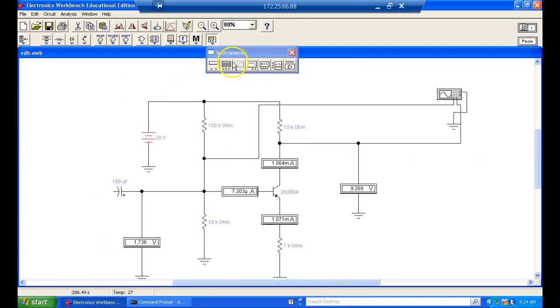So we'll come up here and bring in a function generator. Now normally to troubleshoot these things, audio is all over the place. So to troubleshoot these things, normally we bring in a known waveform. If I bring in a known waveform, then I know what to expect out, right? You understand? So most people that troubleshoot these things have these function generators that they can actually put a sine wave in, and they know what to expect.